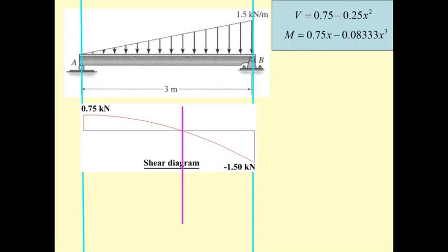that is going to be 9, okay, and 9 times 9 divided by 4, okay, you may get this one as 2.25, and minus 0.75 minus 2.25, you get minus 1.5. This means the shear force changes from positive to negative. So there is some point between the support A and support B in which the shear force is 0.